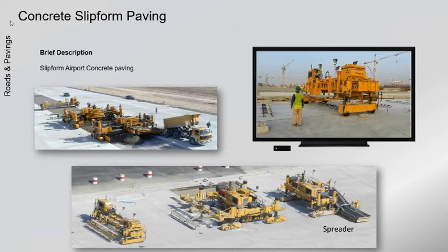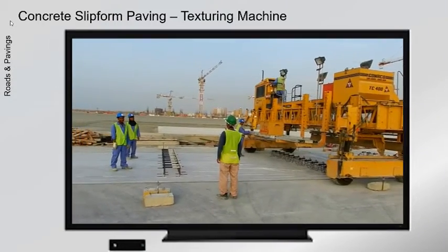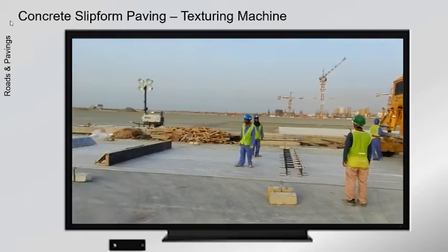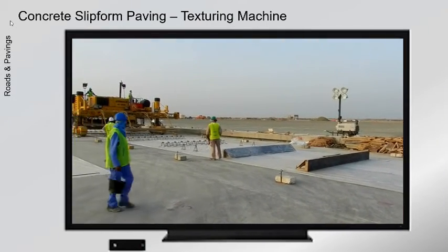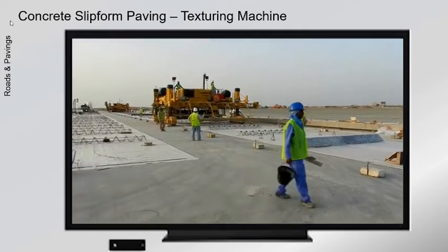Concrete paving. Horizontal slip forming for concrete pavement. The process consists of placing and spreading low slump concrete on the ground in front of a paver that slips over the concrete and extrudes strips of slabs.